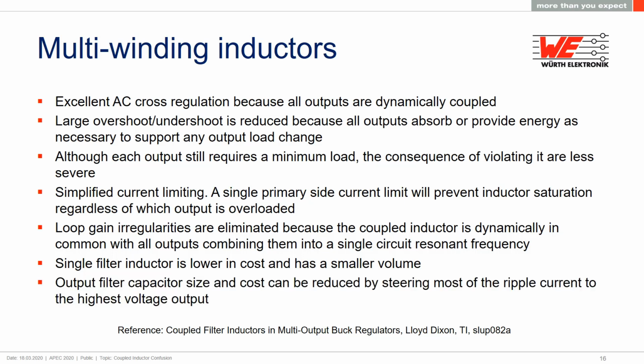And the other thing that you can do is steer the ripple currents to the highest voltage output. Because capacitors store energy proportional to voltage, remember energy is 1/2 CV squared, you can direct the ripple current to the highest output voltage, and you can actually use smaller capacitors in your power supply. A good reference for these is the app note by Lloyd Dixon.